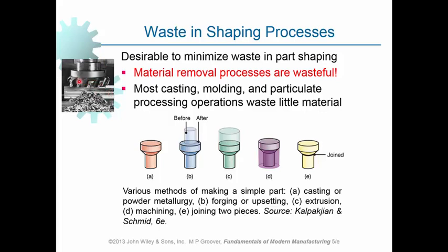And then what is this process doing? It is converting a portion of the raw material. We have paid for it, and we are making use of this process in order to convert some portion of the useful material to the waste, that is the swarf. And this is useless. And again, we've got to pay someone in order to take it away, to remove it. And this could be a hazard to the environment as well.